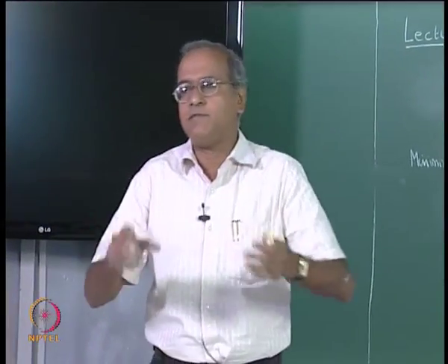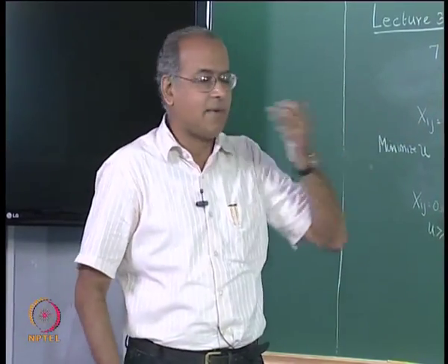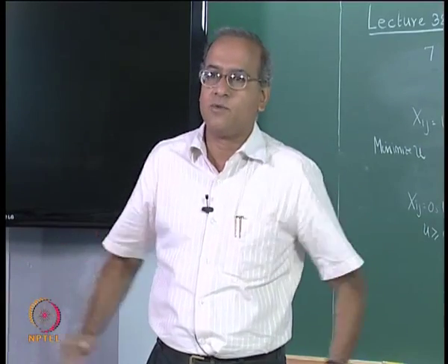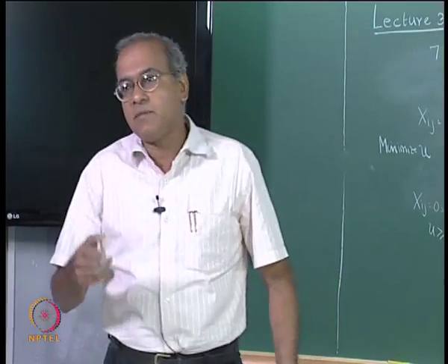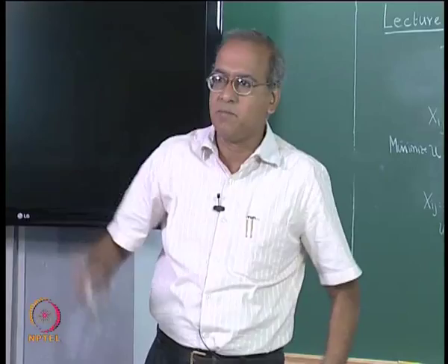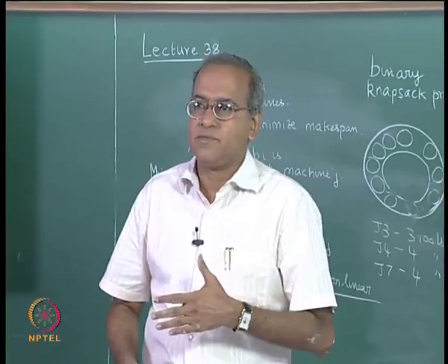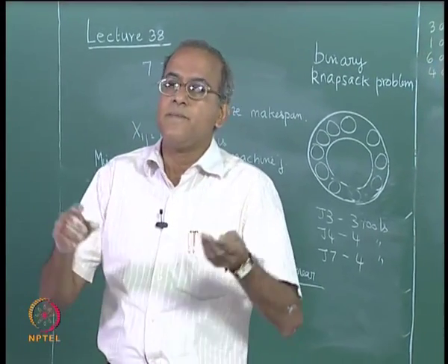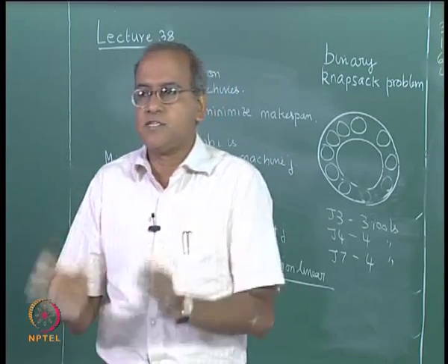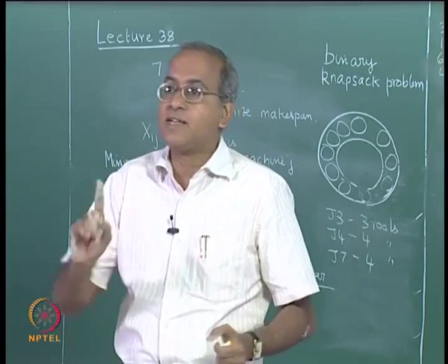But suppose we have about 20 jobs and we have 2 machines. Let us say the tool capacity is 10, but these 20 jobs put together require about 40 tools. Number one, we may have only 20 tools corresponding to the tool drum. The point is now these jobs have to be allocated to these machines, and let us assume for the sake of discussion that the first 10 jobs go to M1 and the next 10 jobs go to M2. The requirement of tools for the first 10 jobs would exceed 10.